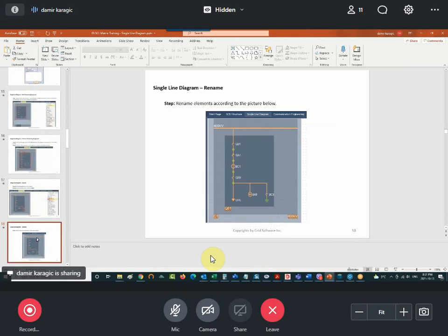So this is the image that we drew, and we'll repeat that, and we'll rename everything according to this image. So first disconnector is QB1, circuit breaker QA1, current transformer BC1, another disconnector QB9, BC9 earthing switch BA9, voltage transformer, and overhead line for the incoming line.